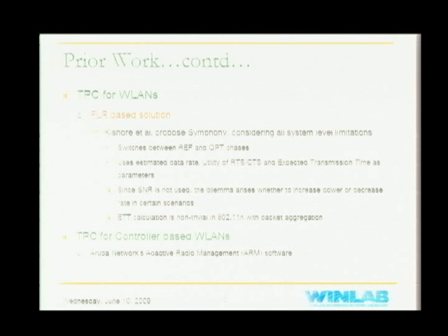But then a change in SNR could also be due to interference or due to mobility. There cannot be a change in RSSI only because of interference. Interference doesn't usually cause a change in received signal strength. Isn't that an SINR measurement? But from our measurements, we couldn't pick up interference using RSSI.